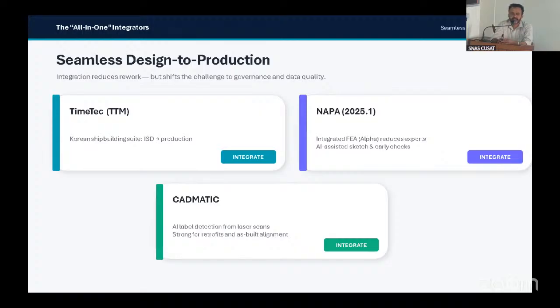We were having one module's tool which was having a bracket. As you are aware, there is a lot of interdependency where your hull girder bending will affect your topside modules. The stresses will be induced over there. And then there is an operational load coming from the topside, which is coming down to your hull structure. So the interfacing point matters. That's where you try to soften your contacts, try to reduce your hotspot so that your fatigue loading doesn't come over there. So that's where you put in the brackets.